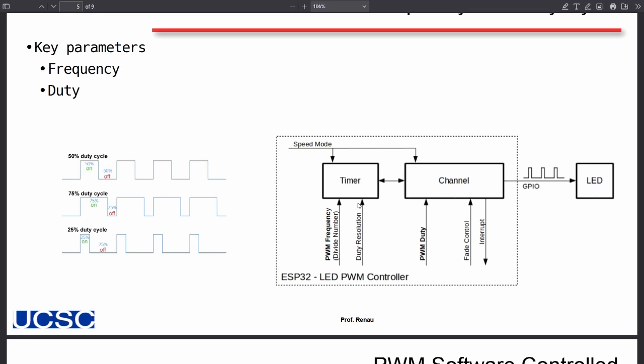And then inside of your PWM channel that you can configure, you just set a threshold value. And you say, once I have gone past a certain count value, maybe the counter will count from 0 to 10, and you say, okay, once you reach the value 8, then output that as a logic 1. Okay, let me write that out.